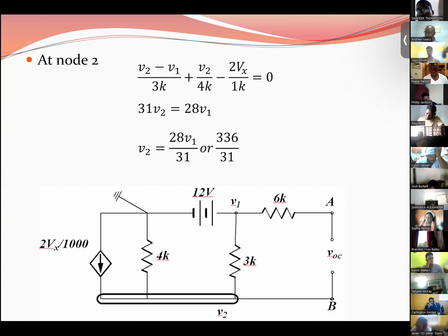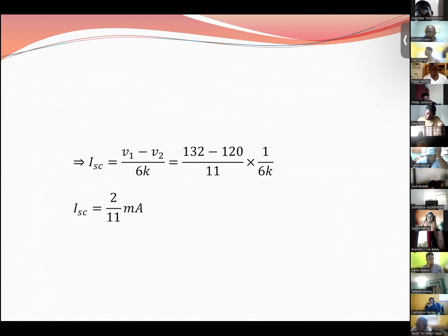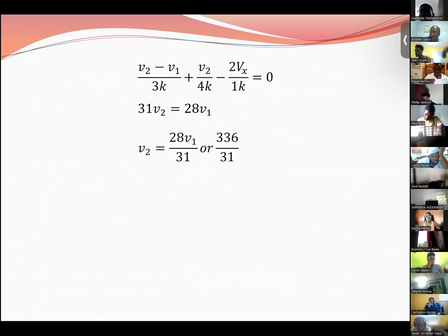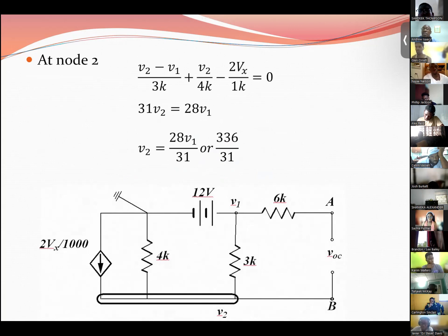Fair enough? So if you look back at the equation, and that's part of the reason why I use nodal analysis, I would have removed this path, the V2 minus 1 over 6. So the equation, I already have it. I've just removed that path and recalculated. V1 is still 12 volts, but for the V2 equation, this is what we now have.